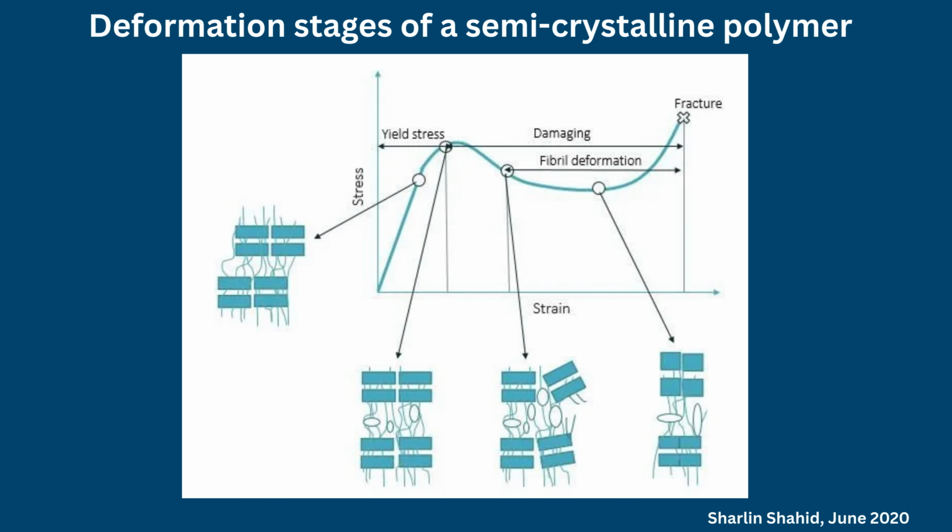Thus, a low Tg provides molecular mobility, whereas sufficient intercrystalline connectivity converts that mobility into macroscopic ductility. This distinction is essential for understanding the brittle to ductile transition (BDT) in semicrystalline polymers.